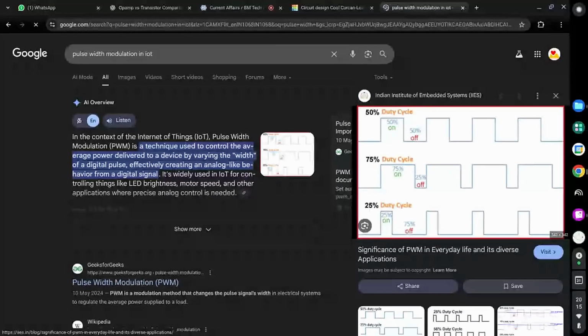Instead of that, you can program it to turn on and off. So you can design it so that the circuit is 50% on, 50% off. When it is on, the voltage is always at the maximum, 5 volts or 9 volts, however you feed it. So the voltage through the motor is constant.